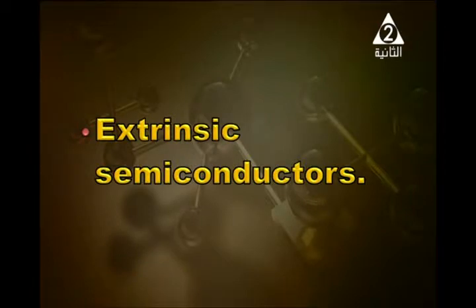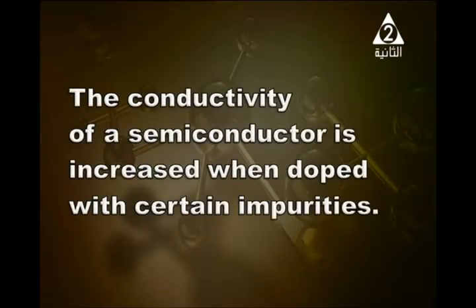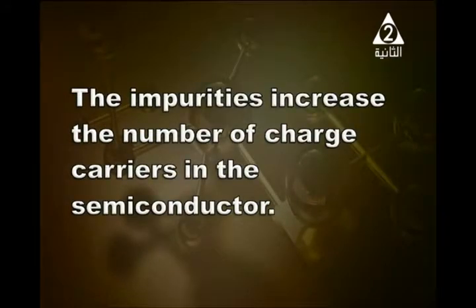What is the idea of extrinsic semiconductors? This is very important. Extrinsic means they have impurities; they are doped with impurities. The idea is that the conductivity of a semiconductor is increased when doped with certain impurities. The impurities increase the number of charge carriers in the semiconductor.